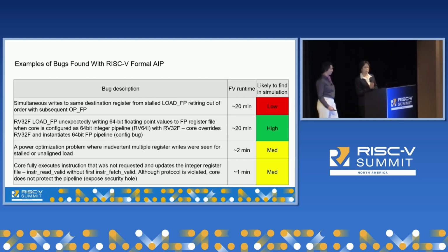The other thing I want to mention, from the earlier slides, is security verification. Formal also has a security verification app called FSV. It's another out-of-the-box solution where you can check for data leaks, whether data can go from a secured region to an unsecured region. You don't want that to happen, so you can use an app for that.